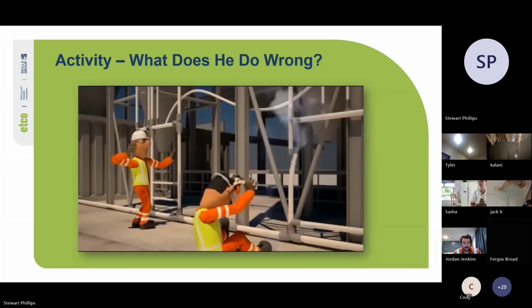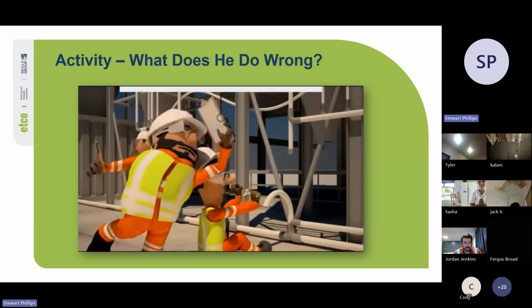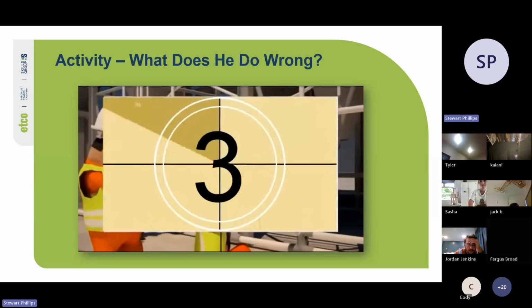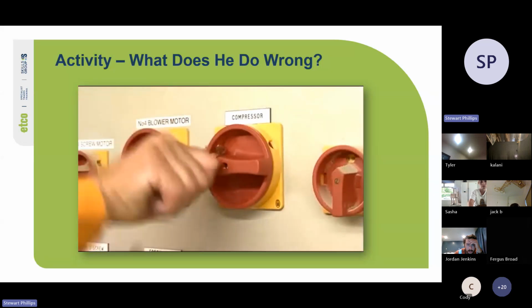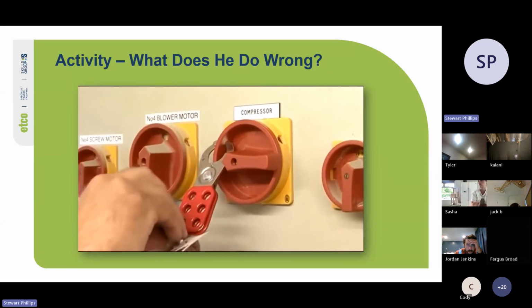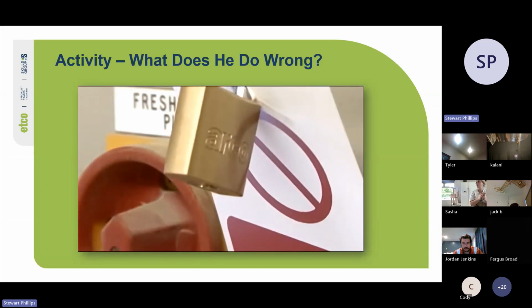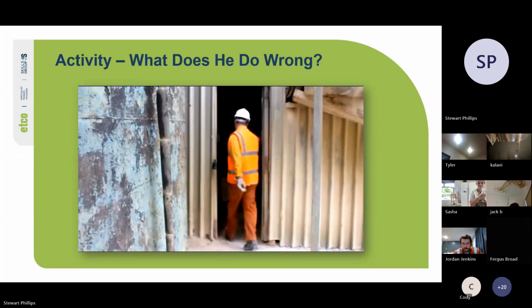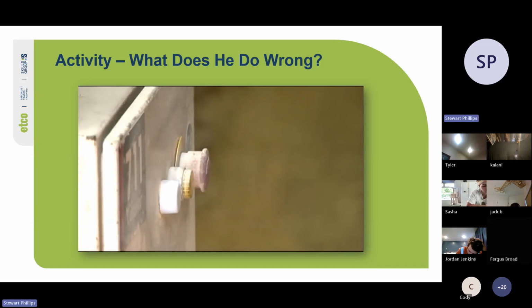Yeah. So here you go. They'd locked it off electrically, but they hadn't removed all of the stored energy, so there was still pressurized air or gas in the line. Compressors turned off. They lock out the machine. Then they go and bleed the system.